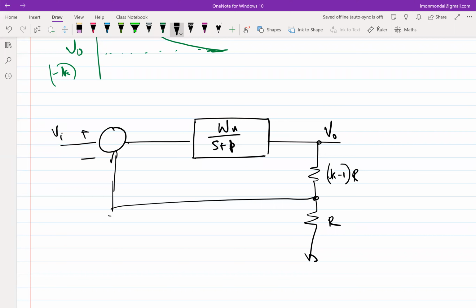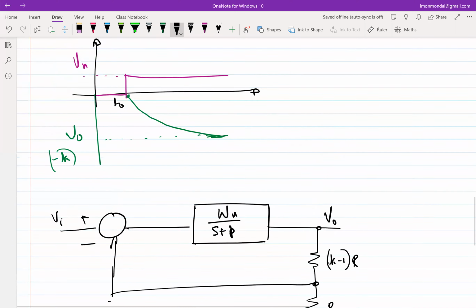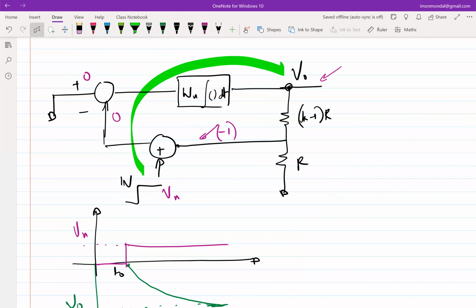Yes. So the take-home message from the last discussion is basically whenever the noise is present in the forward path, that gets suppressed, but if it is present in the sensing path, that will cause a problem, right? So it's always the same scenario in any feedback loop. Whatever is driving the final output, a feedback loop is largely insensitive to changes in that path, as long as the driving strength is large enough. Like in this case, it is infinite, which means that any change in the forward path will not affect the output, as long as your gain is high.